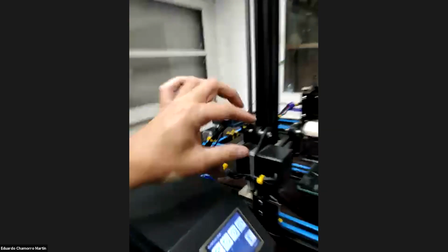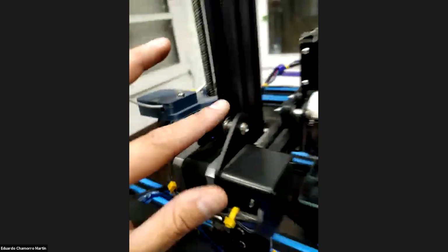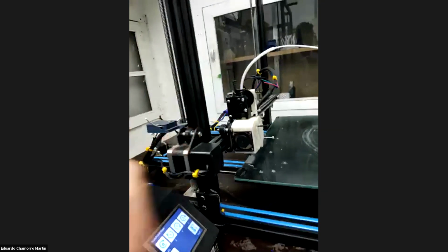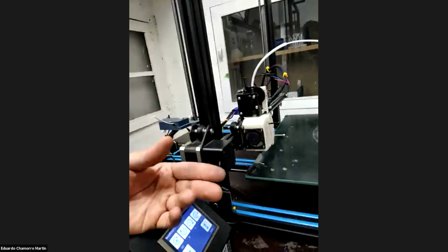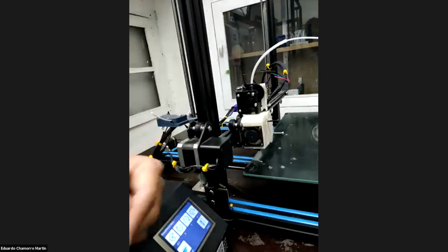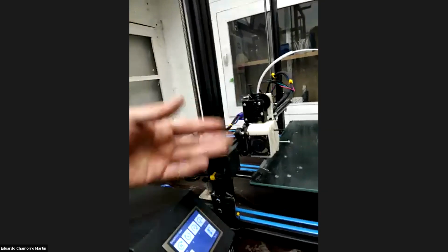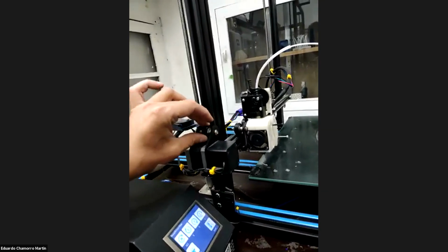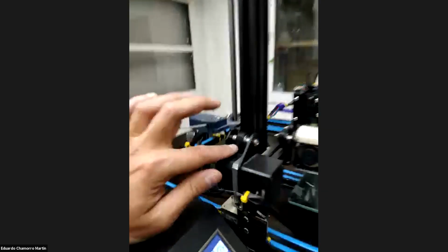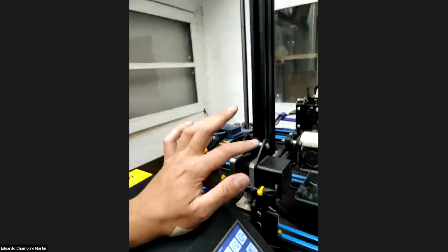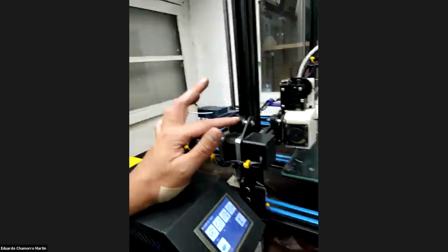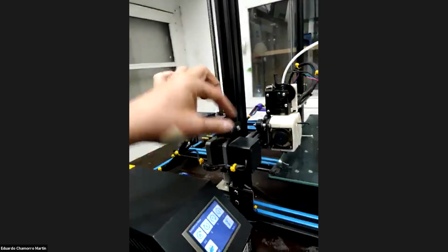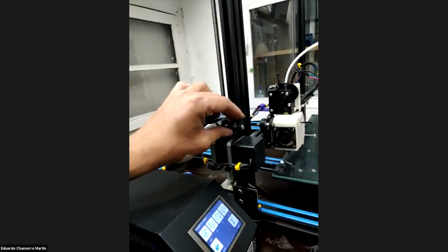What is the problem? It's basically a plastic roller on a surface. The roller, the same as tires, gets worn, so you need to replace it. After like 1-2 years of use, depending on the amount of use, you need to replace all the wheels that are inside. There are also different materials for the rollers. You have this black generic plastic, and you have Delrin, which is a stronger, less frictional material. So these come in multiple materials and formats.